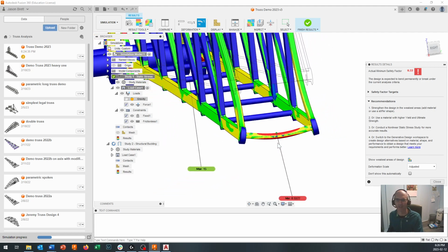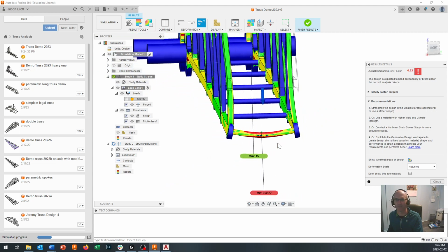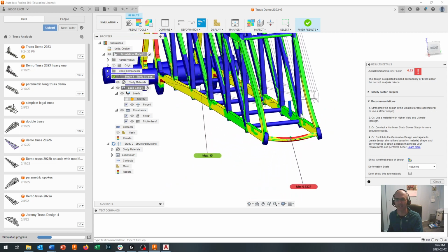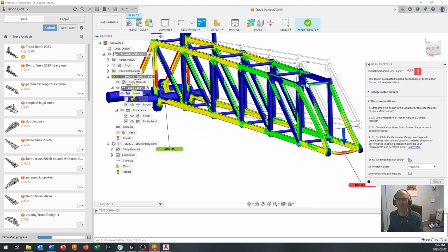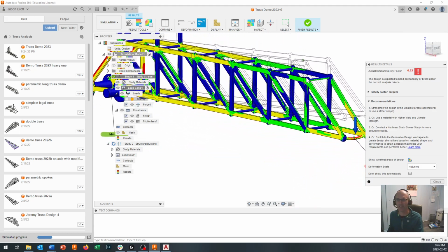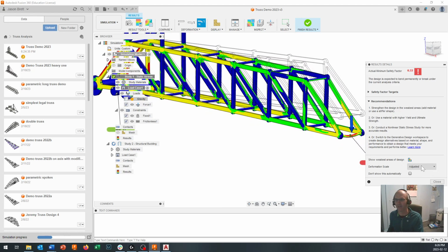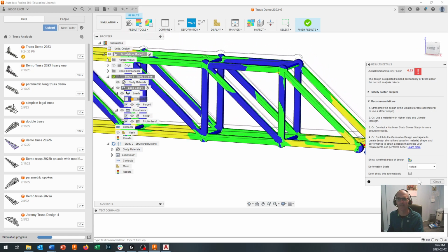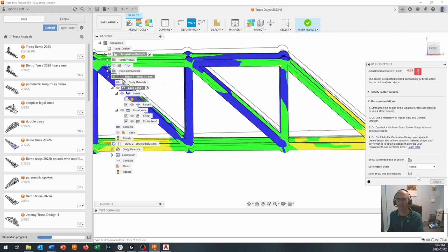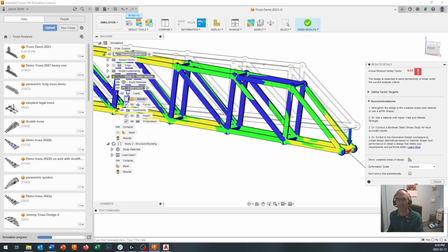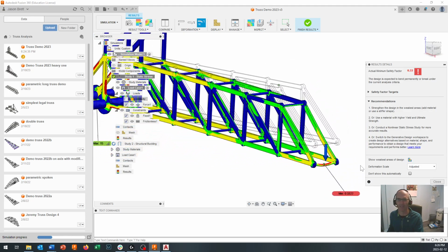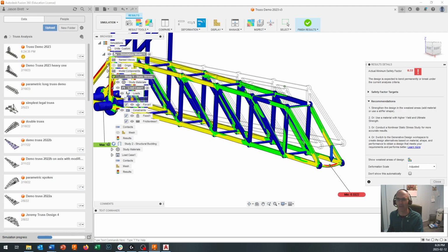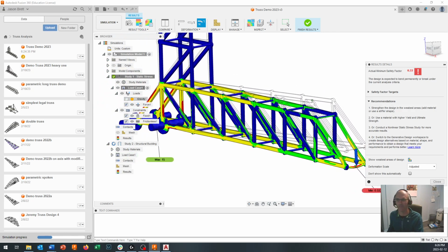It was one of the weak parts of our modeling, but it's probably not too bad. It is applying that stress into the rest of the structure, and we can see a deformed shape right here. Now this deformation is exaggerated a little bit. You see I've got a deformation scale right down here in this dialog box, and if I go to the actual deformation in here, we're looking at a couple of millimeters of deformation, but to really make it stand out, it gives you an adjusted deformation so that you can see where the deformation is going to be happening. So keep in mind, this is a magnified deformation taking place right here.